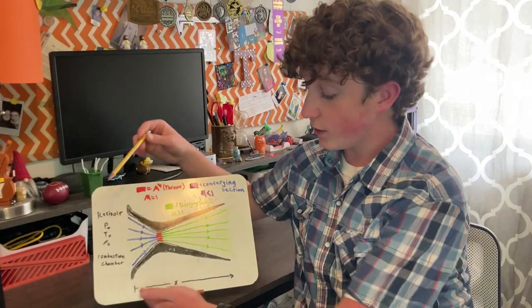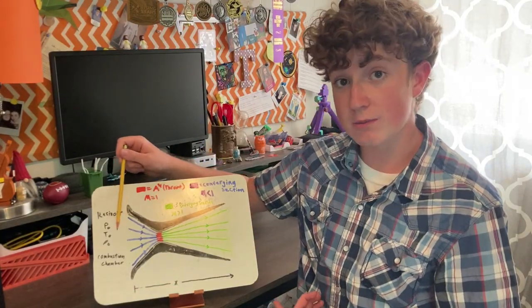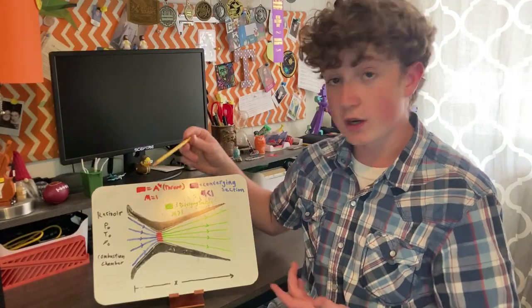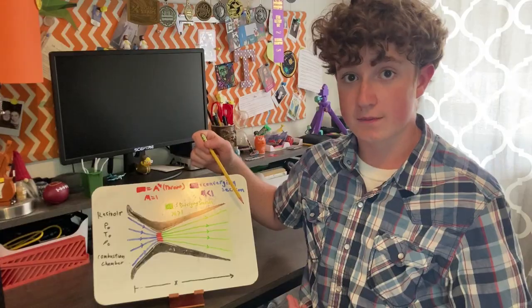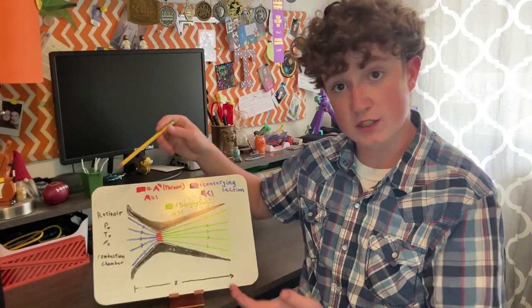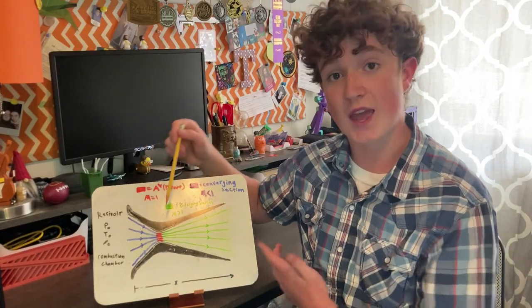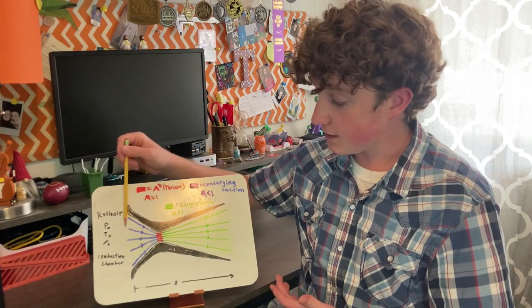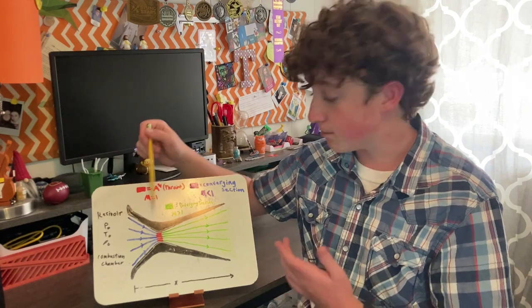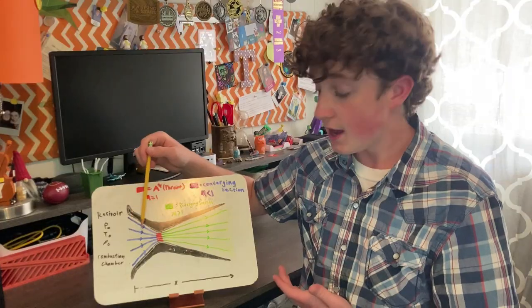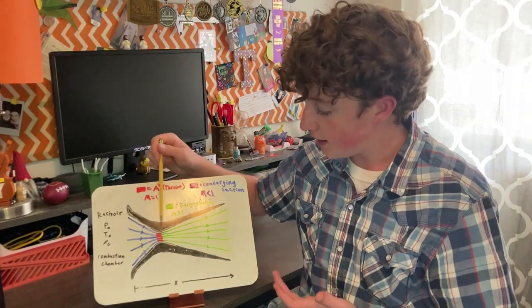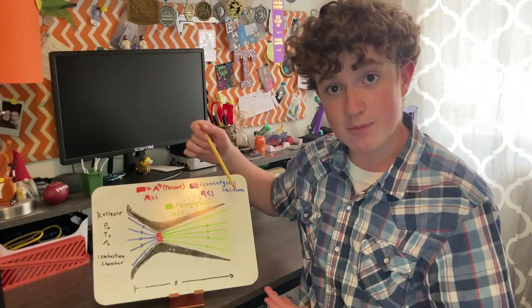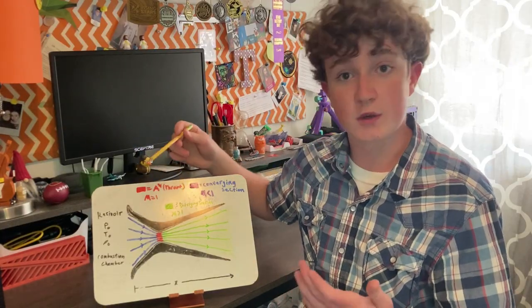As we can see, it is one-dimensional. It flows from the combustion chamber to the exit of the nozzle. We can also see that the mass flow rate is constant, and it has a changing cross-sectional area. This changing cross-sectional area causes the velocity to change along any point x in the nozzle. It starts off at a subsonic speed, where the Mach number is less than 1, and then it converges to the throat where it is at transonic and supersonic speeds. Then, towards the exit, it expands, and that is where we see the increase in velocity.